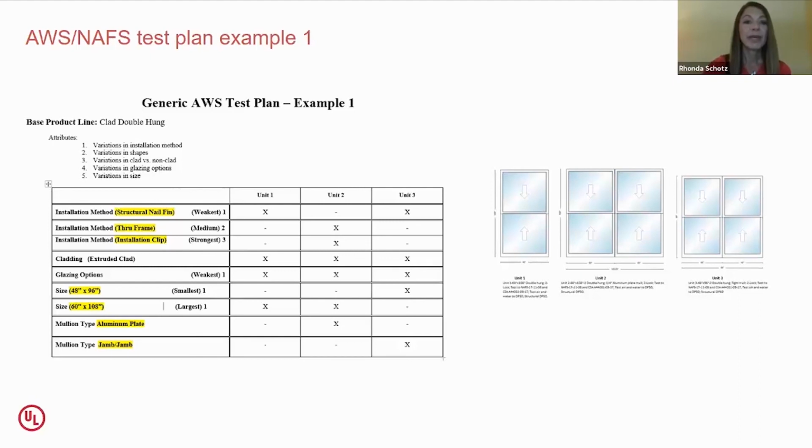Unit 2 makes up for the 3 like specimens. So if you do the first unit and the second unit, all of those are identical units. That makes up your 3 identical specimens. Unit number 3 then is a 48 by 96 double hung mull together with a jamb-to-jamb tight mull. This qualifies per the AMA 450 option 1 again, mullion, testing the total assembly configuration. Again, only for this span and tributary width.